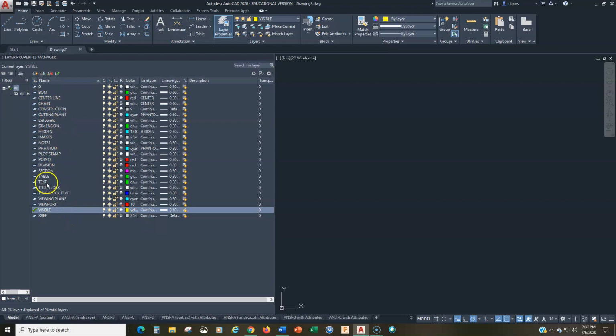All right, these are, of course, layers for an engineering drawing. Okay, so these are kind of standardized. Line weight is standardized between thick and thin. All right, 0.6 is thick, 0.3 is thin. Also, default is equivalent to a thin line also. You can see the line type, and then the colors are just arbitrary. It's kind of a CAD standard in our department for the colors. All right, so let's start making new layers.